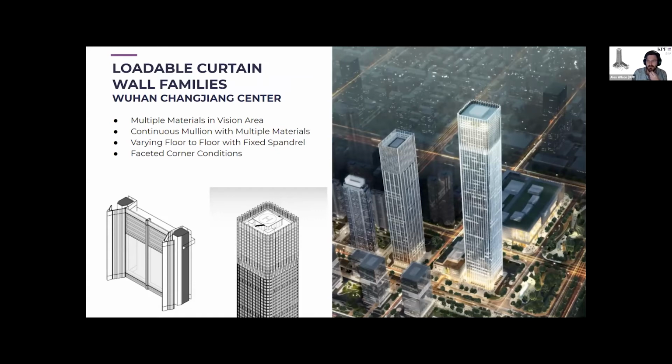We very rarely use mullions within the curtain wall systems. Integrating them within the panel themselves just allows you to do mitered joint conditions, multiple materials per mullion, multiple extrusions on the profile, things like that. It's a vertical facade. There's no slanting or sloping. There is some 3D play in the facade. You can see at the crown, although it's not a very clear screenshot, it goes from a flat facade into a chevron and through a three floor changing of the facade.